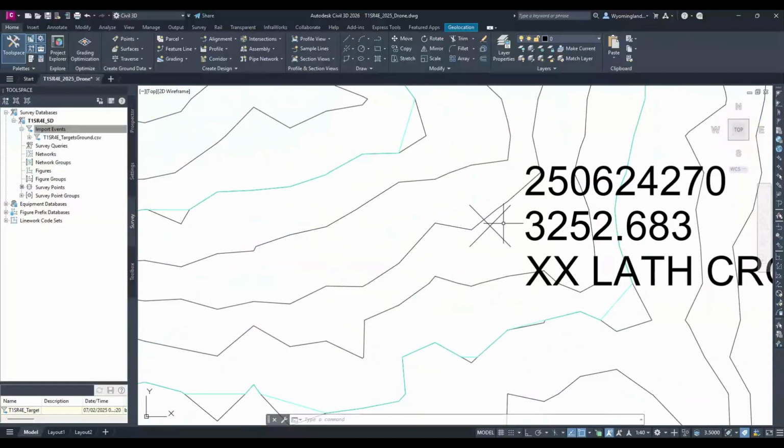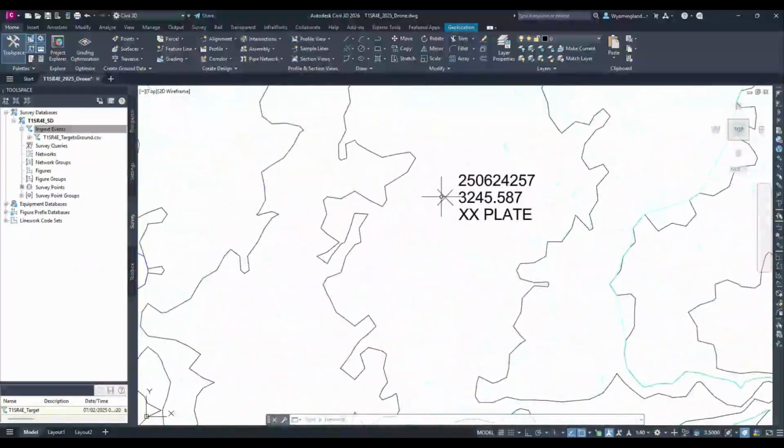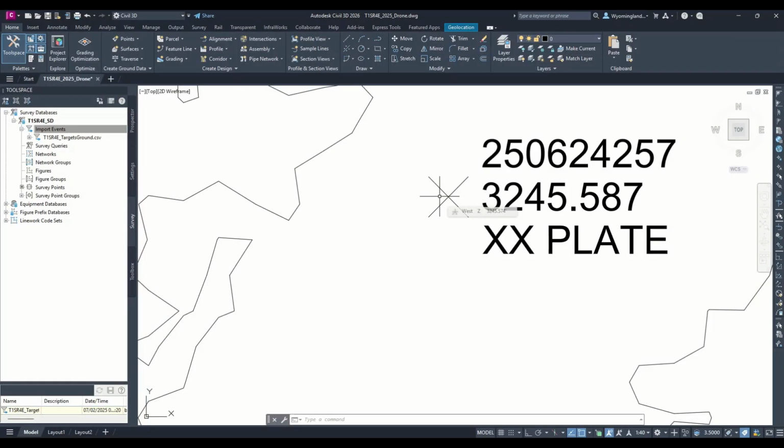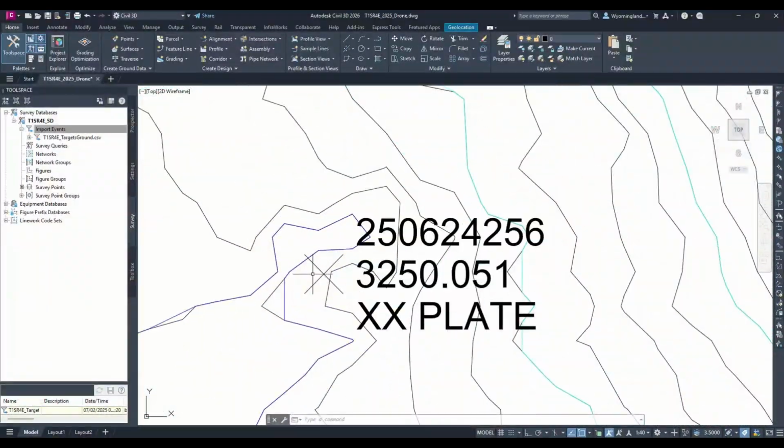Make sure that 95% is going to meet your contour interval. And the reason why I use PPK and do not actually select the targets is to leave the error where it lies. And in this case, by doing so, you are kind of safeguarding not introducing your own pointing and clicking errors into the data set.